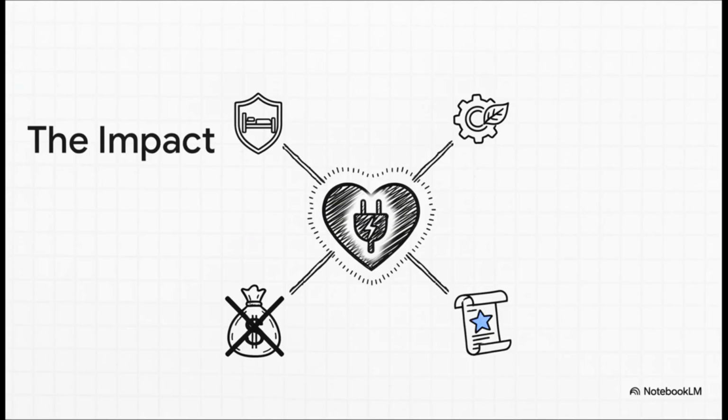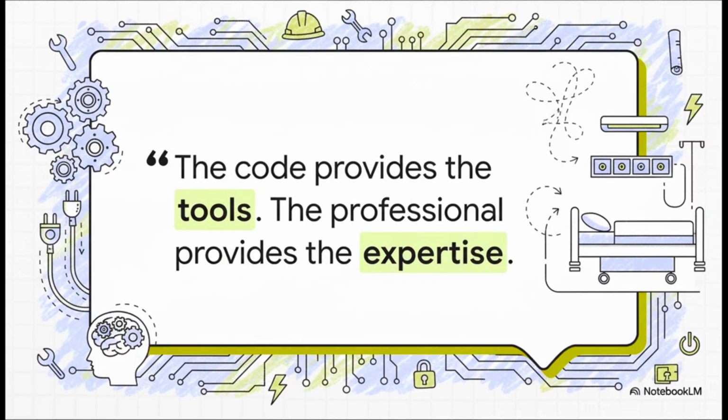In a surgical suite, you could have monitors, a robot, lighting, suction, all drawing heavy power simultaneously. You can't assume the same diversity you'd find in a regular patient room. That higher assumption, that 50% floor, forces the system to be robust. This has been a really amazing breakdown. We've gone from this huge, complex document all the way down to two very specific tables that can dictate the safety of a multi-million-dollar project. It just reinforces that you have to read the code for the philosophy behind it. Yeah. These tables aren't arbitrary. They're based on decades of data about how power is actually used in these high-stakes environments.